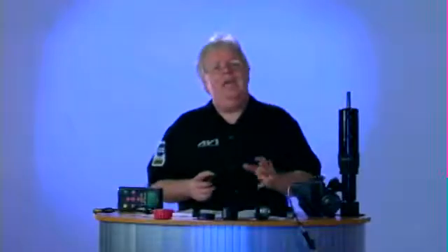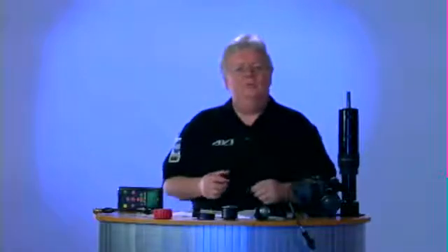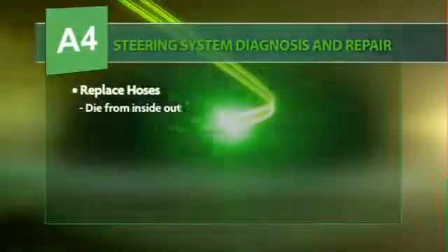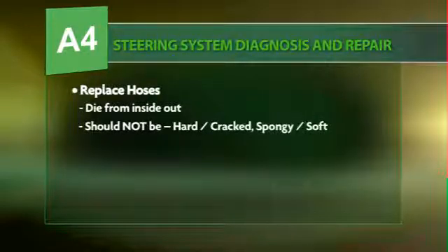So then you have to look at where the air is getting into the system, tighten up hoses, find leaks, and so forth. Now, let's go down to the hoses. They die from the inside out, and they should not be hard or spongy.